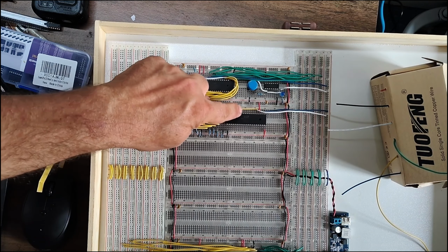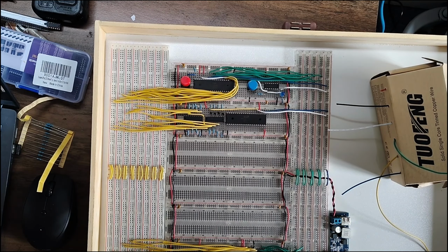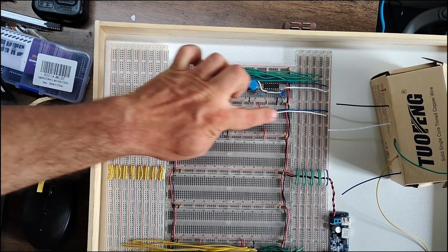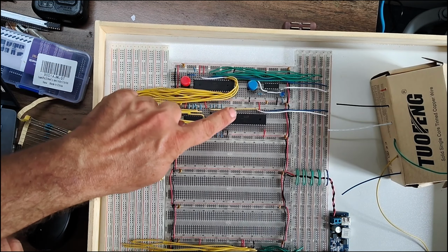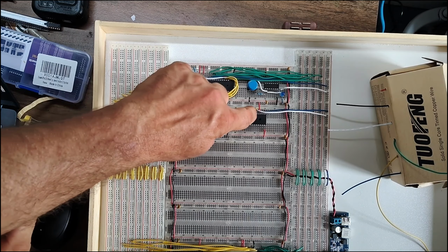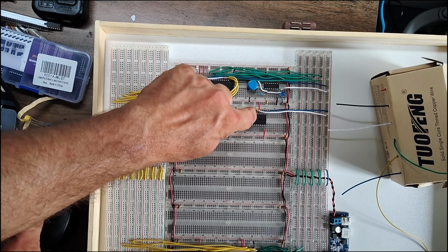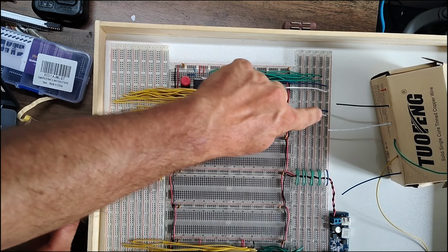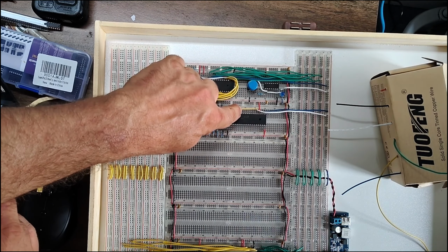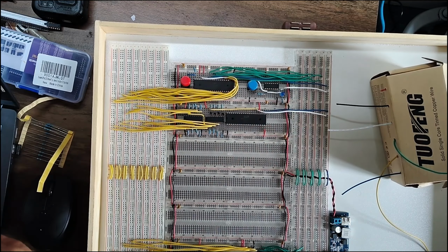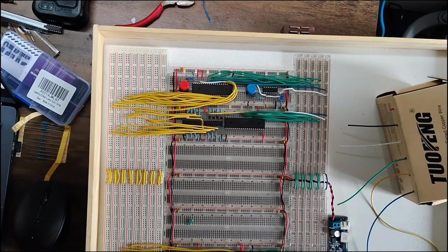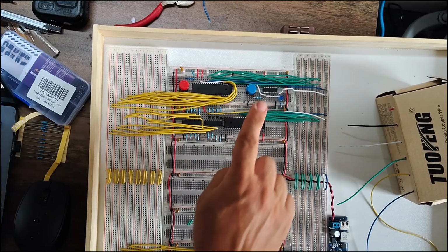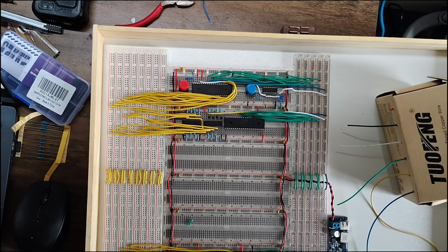And then these next pins, the next 8 pins, are all data pins. So they need to go across to here. And just like on the 6502, the most significant bit, which is pin D7, needs to go the shortest distance, and then needs to go further and further across to the least significant bit, which is the furthest away across to there. So I'll get those 8 data lines connected up. That's our next job. Right, there are all 8 data lines connected up.